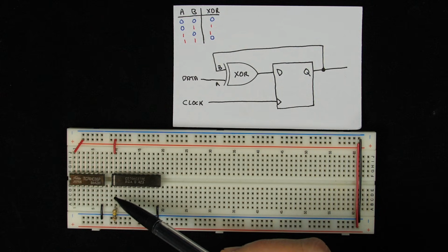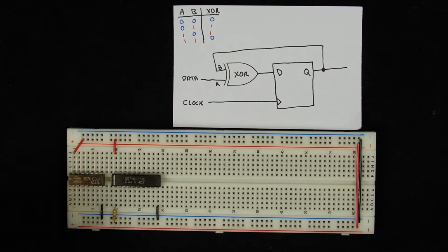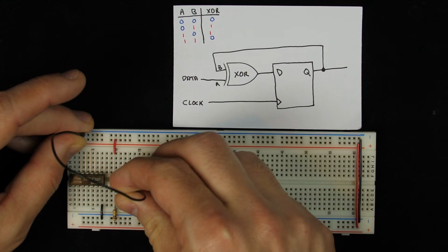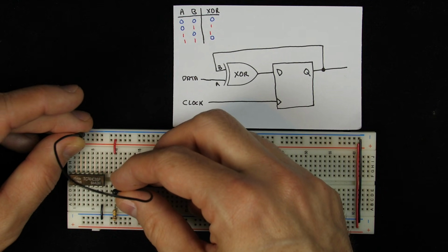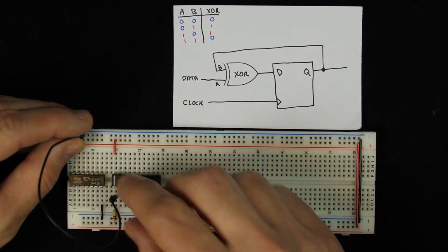And the way this pin works is there won't be any current flowing through the resistor, so both sides of the resistor will be at 5 volts. Which means pin 1 will be high. But if I want to manually reset it, I can just use a jumper like this and connect pin 1 to ground, and that'll reset it. And having the resistor here will just keep us from having a short circuit when I do that. So that's the clear pin.